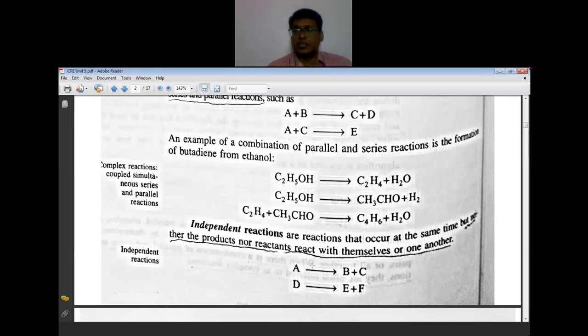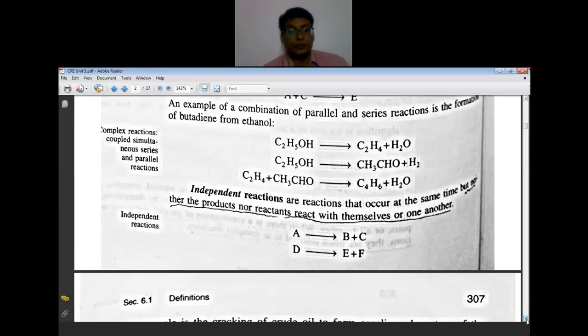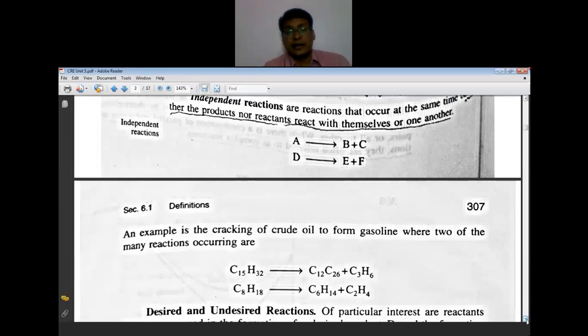Now in the general case we say that 99% is the pure reactant available for the reaction. However, it may contain 1% or 0.1% or 0.01% impurities, and this 0.1 or 0.01% may change and affect your product pattern also. So in general, industries prefer the same raw material company. They don't switch over, and if they want to switch over, they do it with trial and error only.